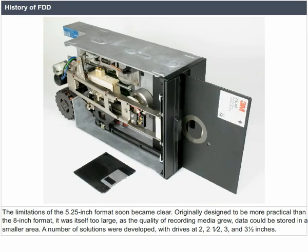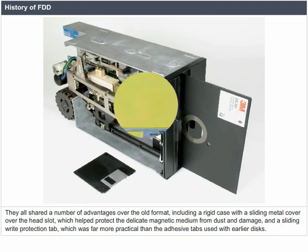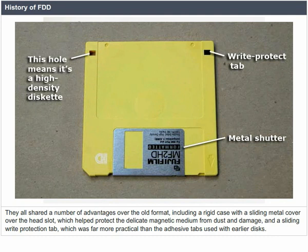The limitations of the 5.25-inch format soon became clear. Originally designed to be more practical than the 8-inch format, it was itself too large. As the quality of recording media grew, data could be stored in a smaller area. A number of solutions were developed with drives at 2, 2.5, 3, and 3.5 inches. They all shared a number of advantages over the old format, including a rigid case with a sliding metal cover over the head slot, which helped protect the delicate magnetic medium from dust and damage, and a sliding write protection tab, which is far more practical than the adhesive tabs used with earlier disks.